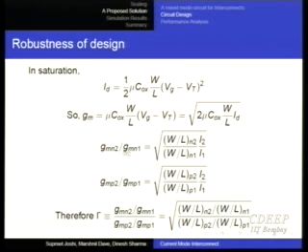So essentially gmN2 by gmN1 is the ratio of the two N channel transistors, because both are N channel. Therefore mu and Cox cancel for both of them. However, the currents are potentially different in the two. Right? So therefore this ratio is root I2 by I1. But similarly gmP2 by gmP1 is also root I2 by I1, apart from geometrical factors. Right? So when you take the ratio of ratio, because the N channel and P channel are in series, the current therefore is the same, so now the current cancels out.